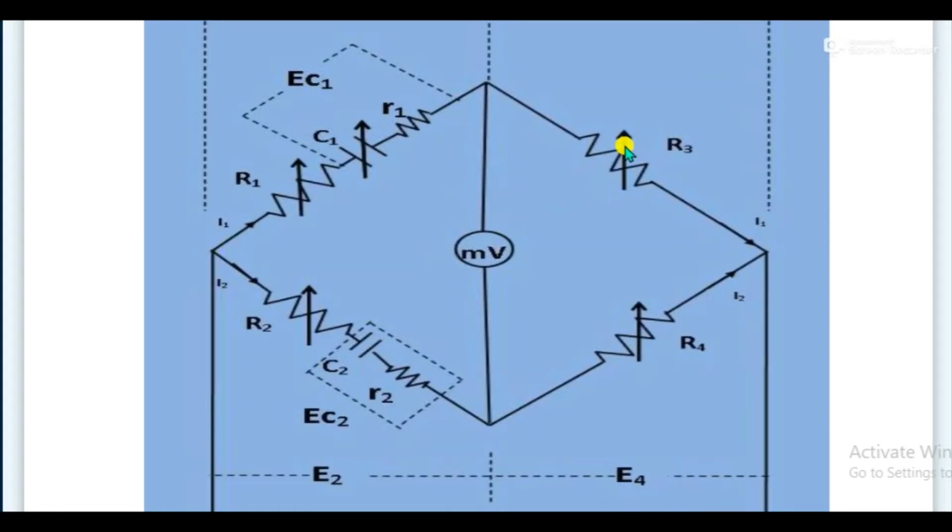So in Wheatstone bridge, what we had seen earlier was that here is the resistance, here is resistance, here and here also. Main concept was the ratio of the resistance. Here, in this wire, no current passes through it. It means the null detection. Also sometimes this is asked in Viva, that as a whole, in a single word, how can you describe the principle? So that is null detection method. It is also known as where the current does not pass through this wire. This means that the potential at this point and this point is the same.